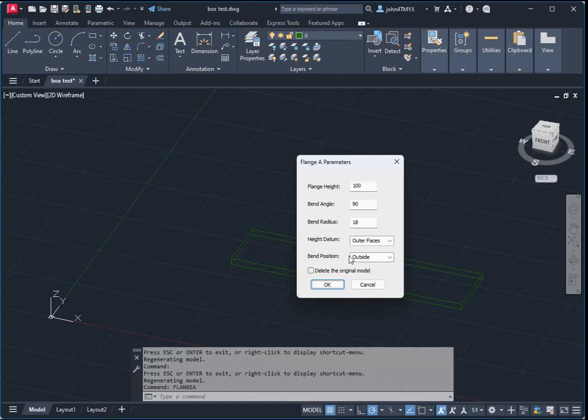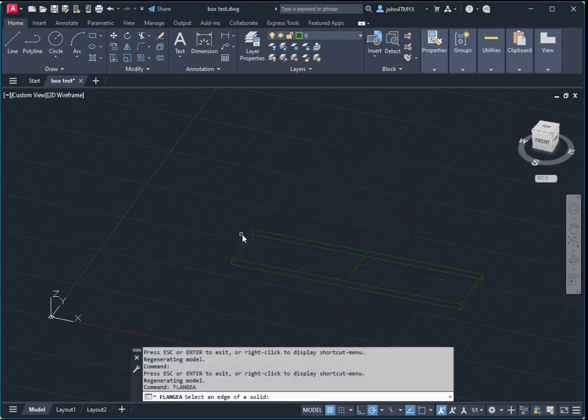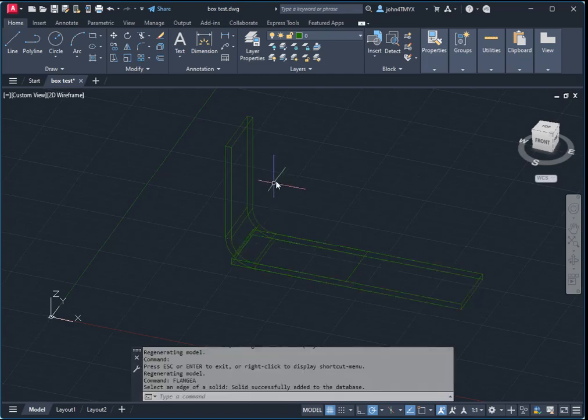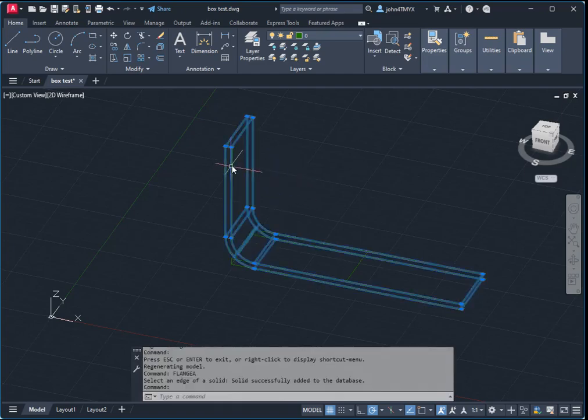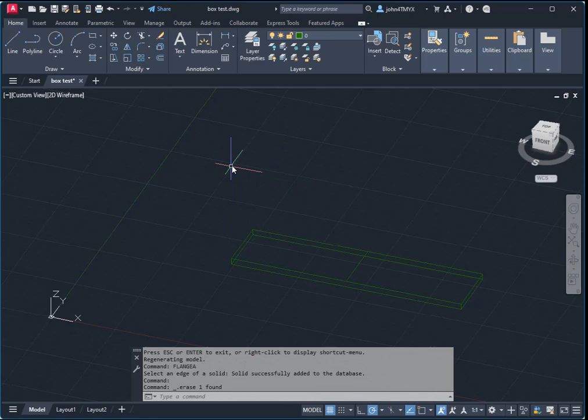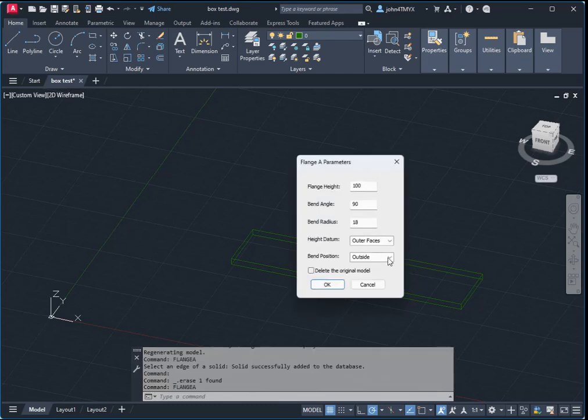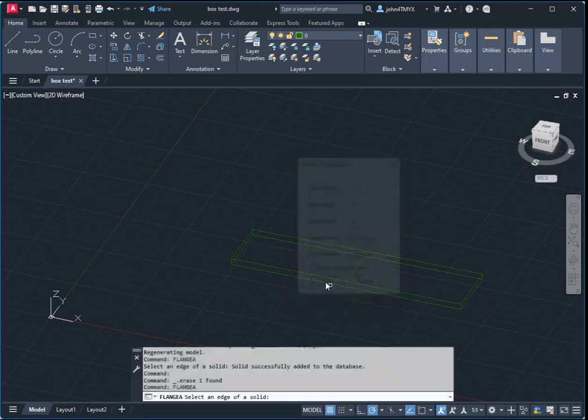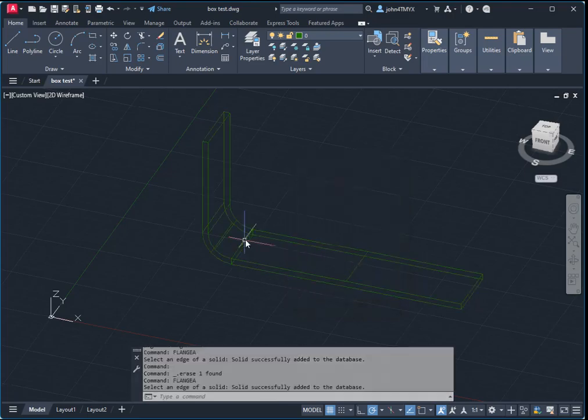Basically, it's used to define the baseline for the flange height relative to thickness, and relative to the original shape of the plate. Click OK, then click here, and you can decide the shape you want. For flange A, for example, you can choose an adjacent edge, and click OK. This is attached to the plate.